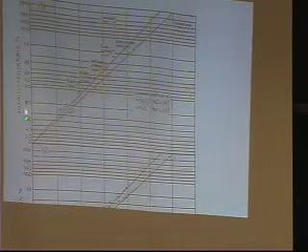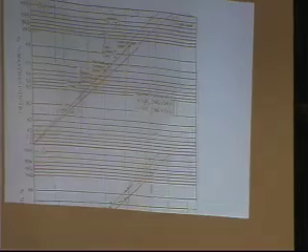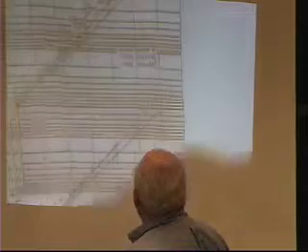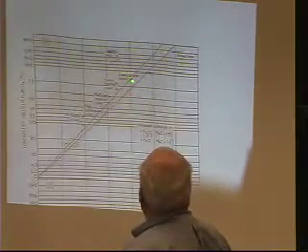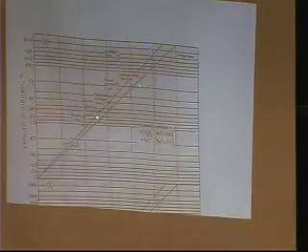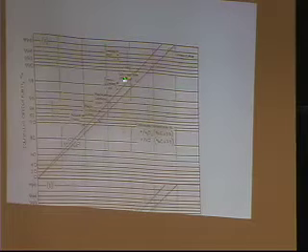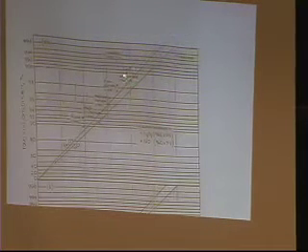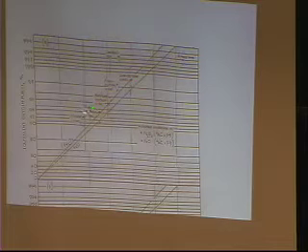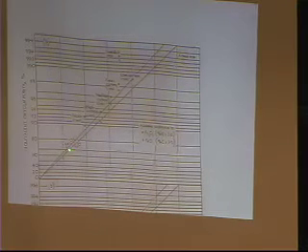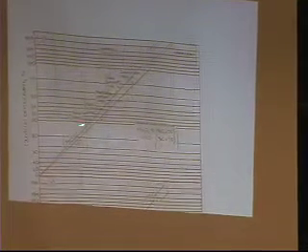Cutting, he calls it the equivalent oxygen purity, and what's on the bottom line here? The bottom is relative combustion rate, okay? So 1.0 is cutting of low carbon steel. If you have Armco iron, which is very low carbon, or Swedish iron, which is also extremely low carbon, probably 10 times lower than low carbon steel. And then he has medium carbon steel, high carbon steel, razor steel. Razor steel is like over 1% carbon. It's not cast iron, but it's getting up there. And cast iron would be way down here somewhere. Cast iron doesn't cut very well.